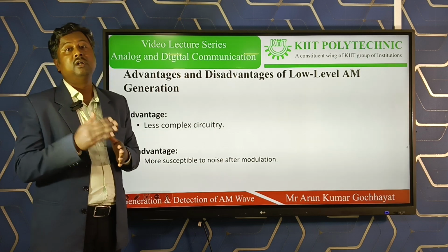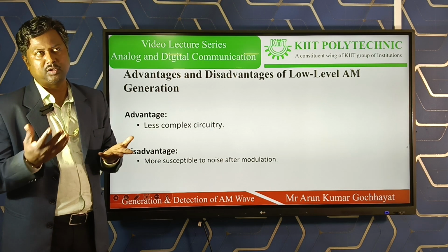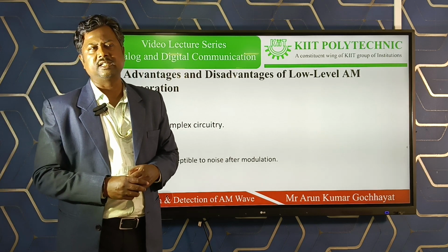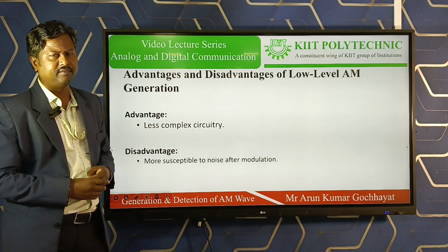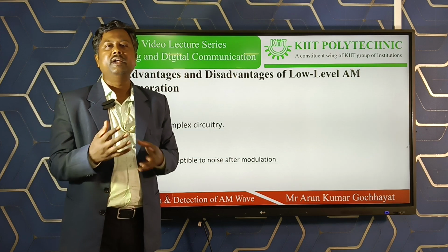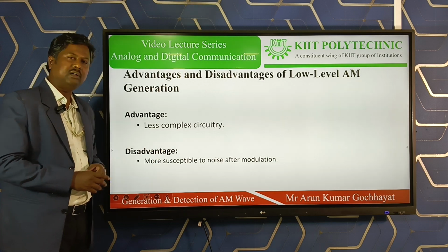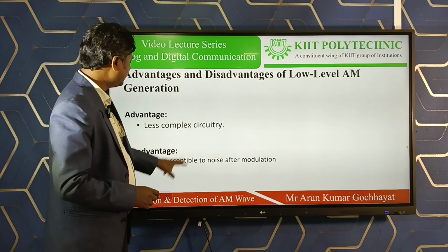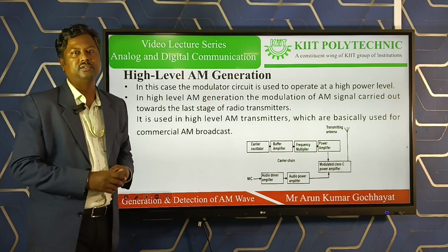Means after modulation, when the signal is transmitted to the channel, in modern communication we are getting a non-physical channel, that means a wireless channel, where the signal is exposed to the whole environment. So in that case, if the modulated signal is kept at a low level, it will become more susceptible to the noises or distortions in the environment. So that is the disadvantage of low level AM generation.